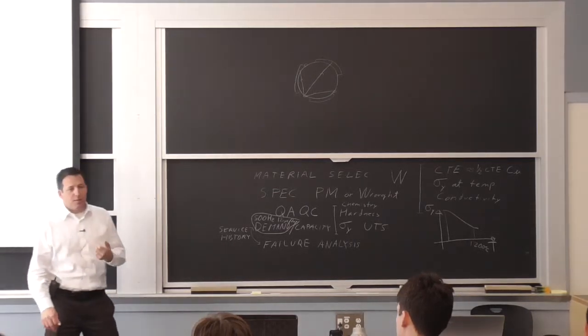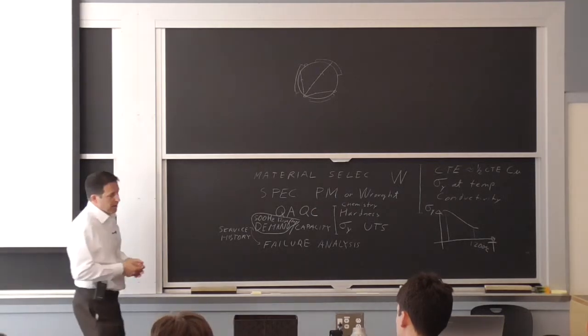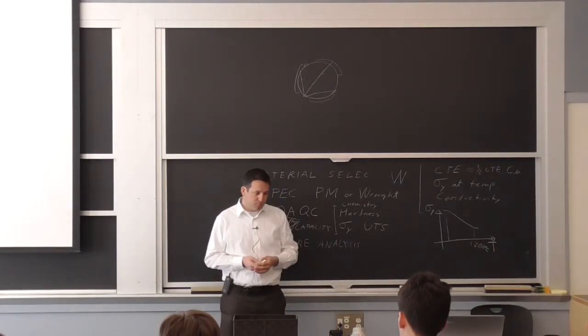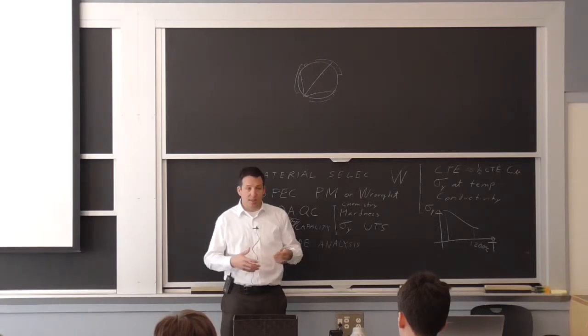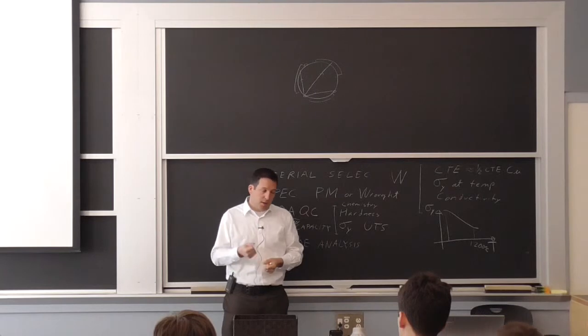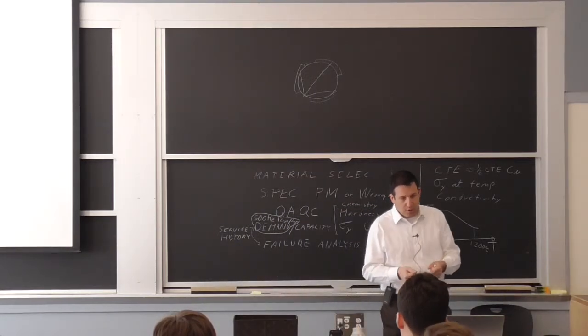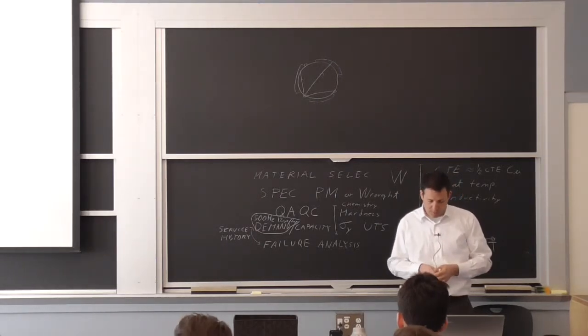So think about it, the first time when everything is cold and you hit that surface, all of a sudden the target really wants to expand. It's the same when you shut it down. Now all of a sudden what's on the surface is the one that's getting the biggest temperature decrease and wants to crack. So it's in the cooling part that you get the tension on the target, and it's the other way around with respect to the substrate.